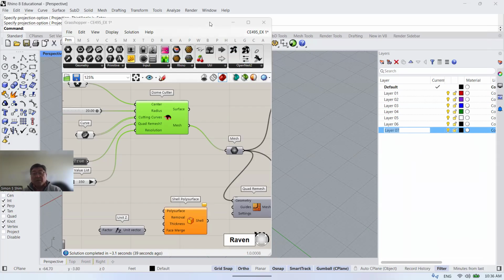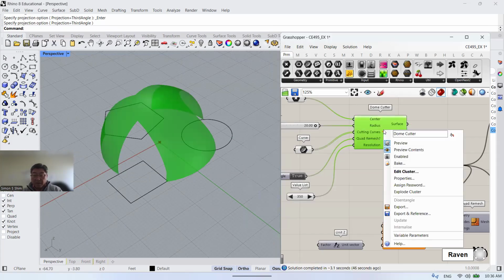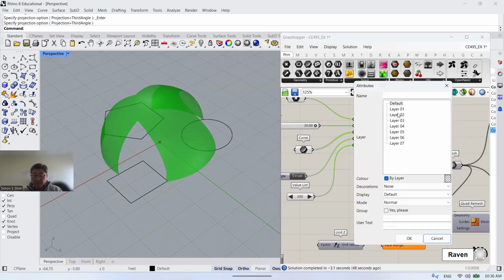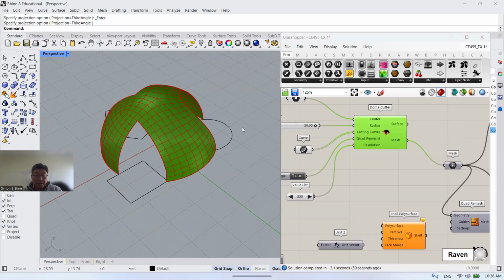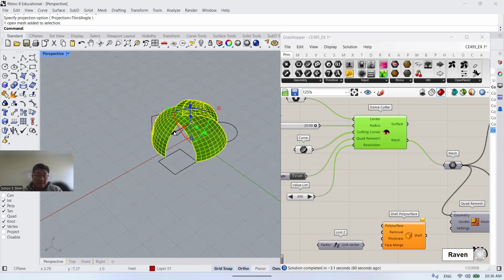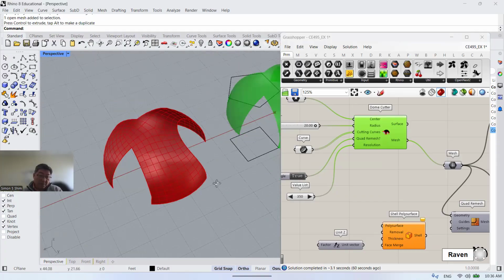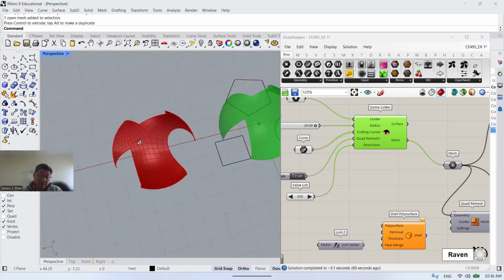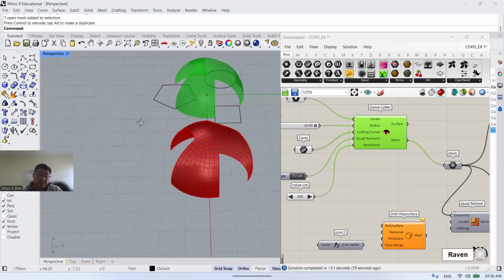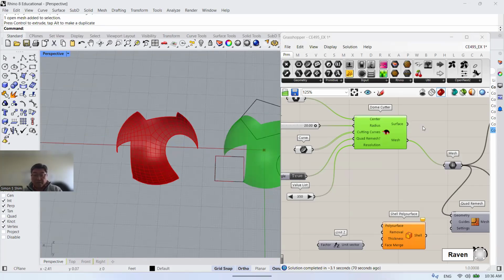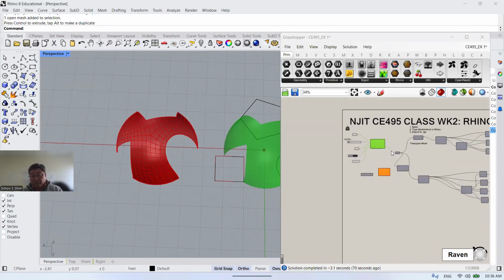So this is something similar to AutoCAD, it's a layer. So again, if you click this, right click, you can bake it to any layer. When you bake it, this is one single mesh. So I'm going to choose any layer. I bake it, select it, and move it away from the original point position. Okay. At least you have some sense of this, because this is eventually a long learning procedure.